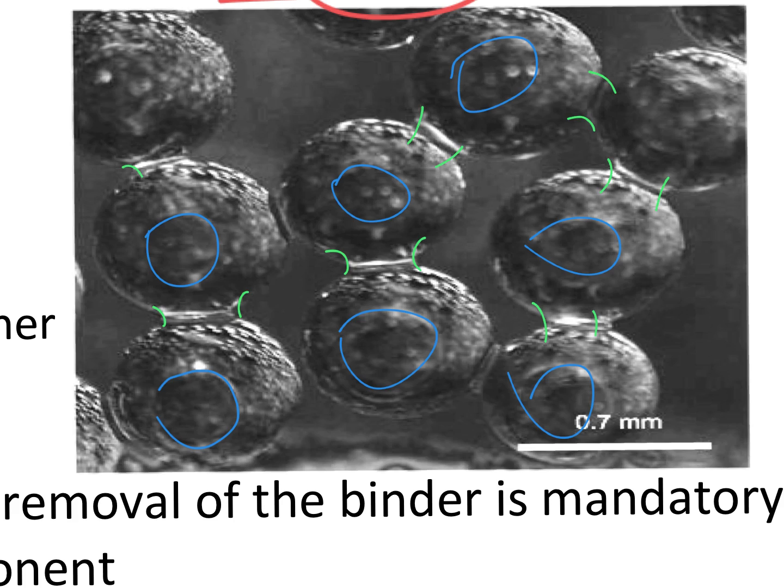What I want you to take away from this is that this is kind of the goal state for a lot of MIM. We only get to this goal by removing the space between the beads up to the point at which these necks are formed. But we need these necks to stay there. So what we're going to be talking about is MIM that uses this strategy, which we injection mold with an easily removed organic phase, and then we also have in there an organic phase that is not as easily removed. But it gets to this point where the bridges are a certain size and they can exert F sub c's that are relatively large and hold everything together. Is that clear? Is this image clear?